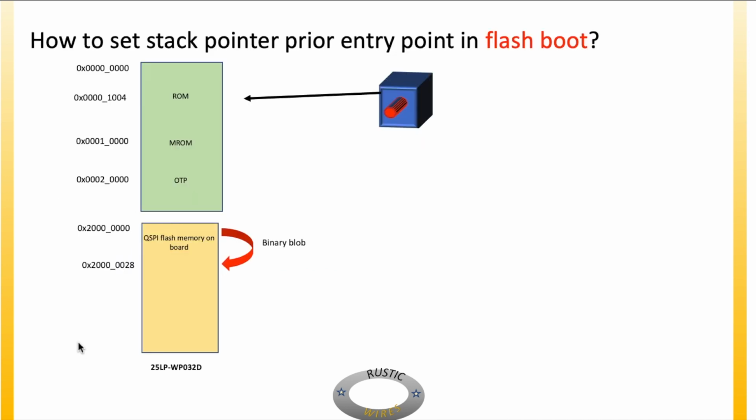Okay. So now when I boot from Flash, I haven't observed this before when I executed the code from RAM, but when you boot from Flash in the HiFive1 revision 1B board, this is the boot sequence, and whatever is highlighted in green is fixed at the manufacturing of the chip itself, and we have no liberty to modify any of this.